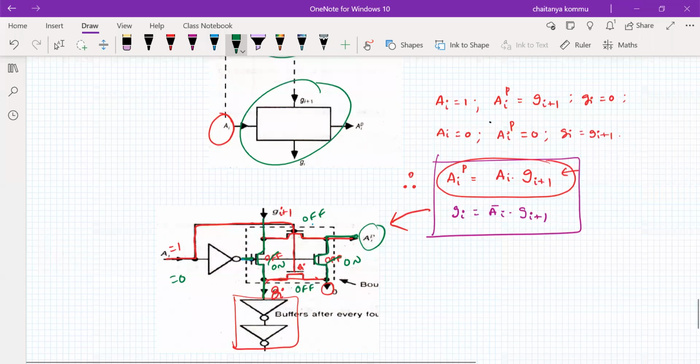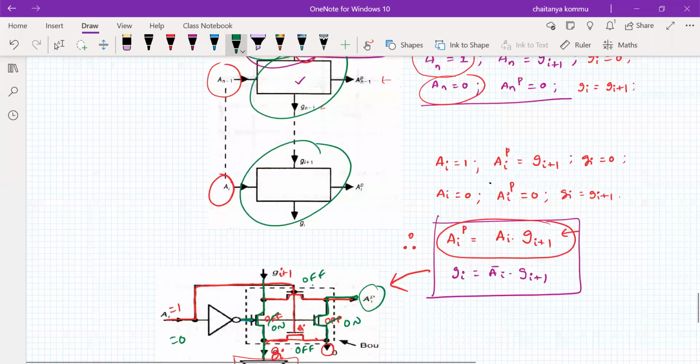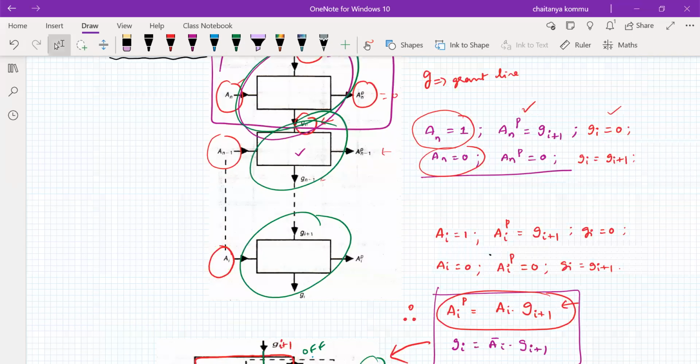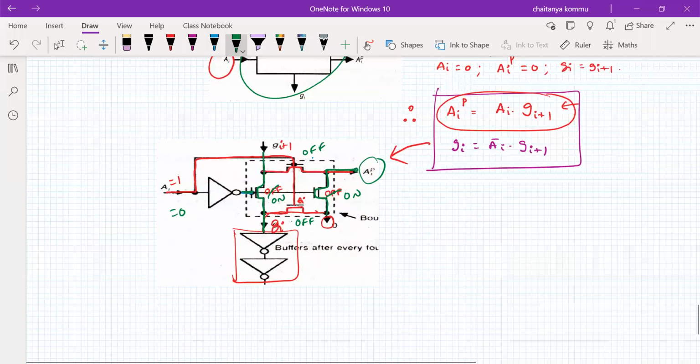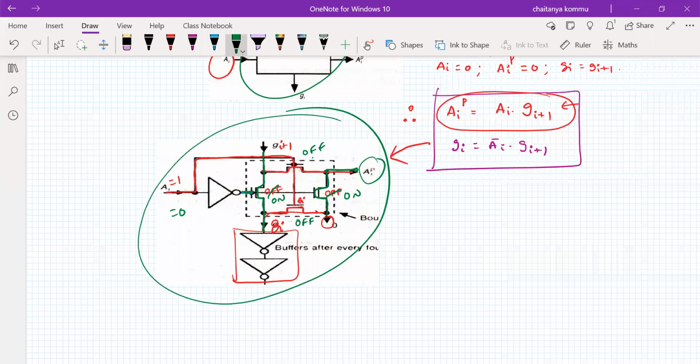So therefore, we have to use this as many times as there are input bits; that many blocks are required. This is called an n-bit arbitration network. It is simply a priority circuitry: which bit has the highest priority and which bit has the lowest priority, that is the priority we have to generate here.